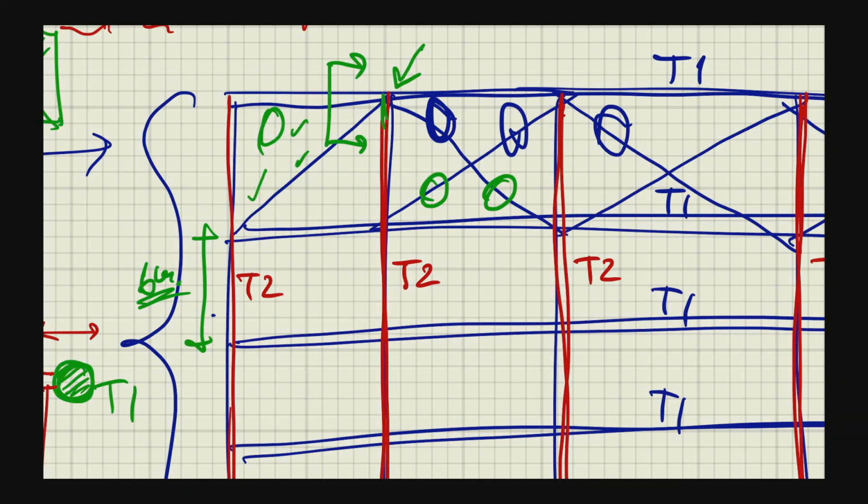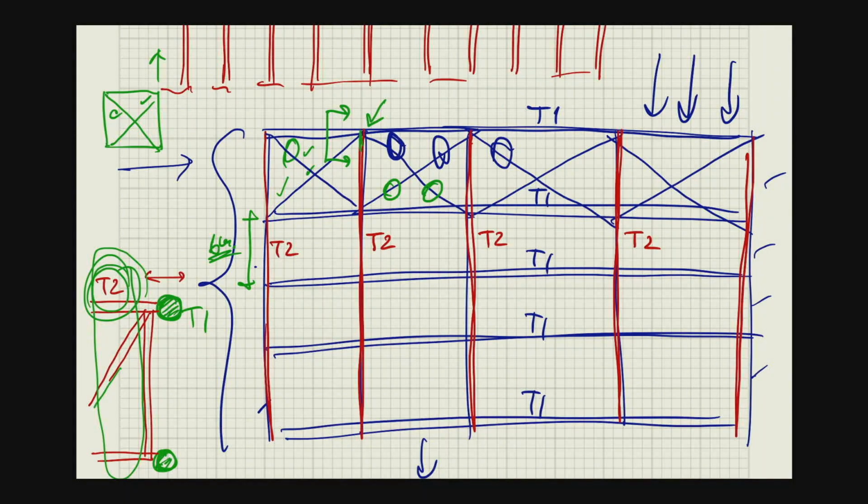Oops. Okay, I put this one. The design of this brace has to be accounted for 1 truss, 2 truss, 3 truss, 4 truss, 5 truss. Very interesting, because you are going to brace in total 5 top chords. Total force is going to be 5 times the PF, or 5 times the moment divided by the depth of the truss.